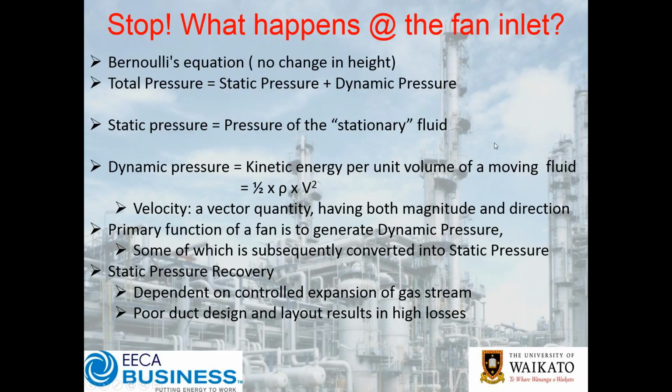Now just on this, just to help us get our heads around it, we want to stop for a minute here and understand what happens at the fan inlet. We did mention this previously in another webinar in terms of Bernoulli's equation. We're assuming here there's no change in height, so total pressure is equal to our static pressure plus our dynamic pressure. The static pressure is the pressure of the stationary fluid. The dynamic pressure is the kinetic energy per unit volume of a moving fluid, or in the equation here, half times rho, being the density, times the velocity squared.